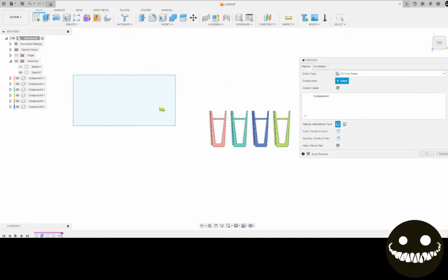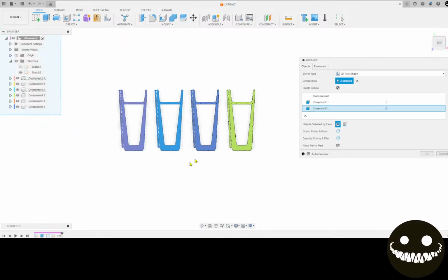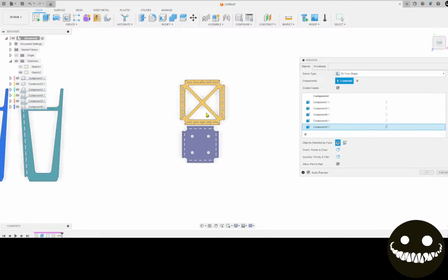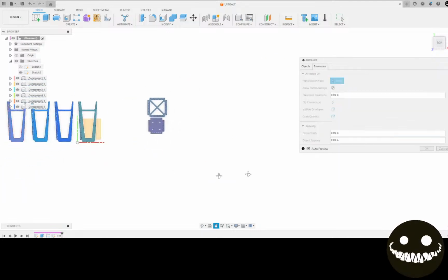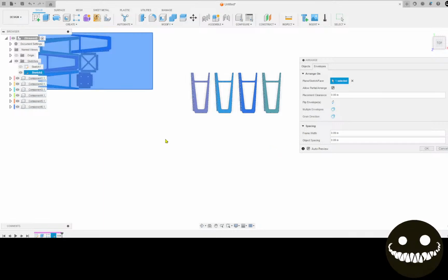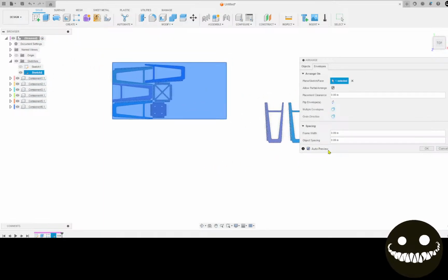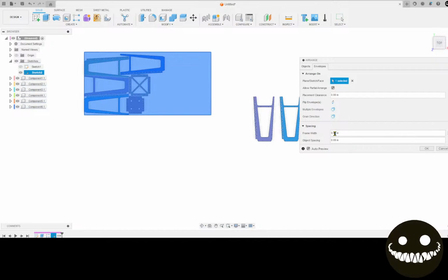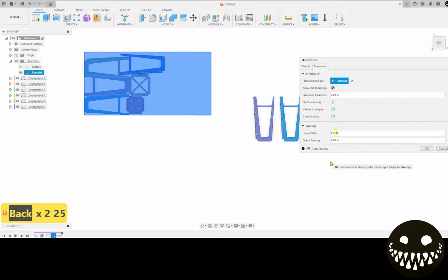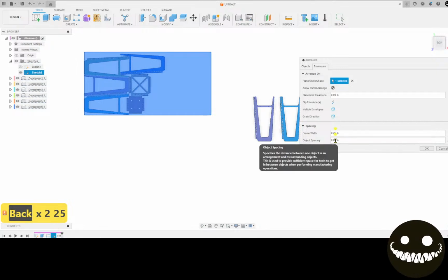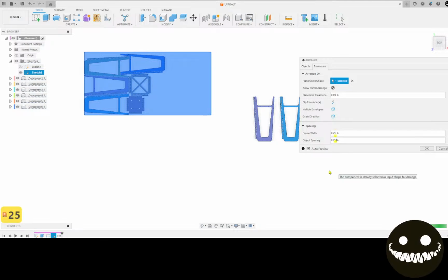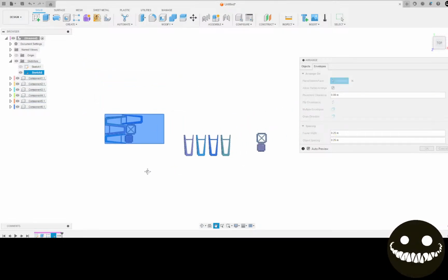Now what I'll do is go into modify and use the arrange tool. Select all this. And we are going to put it into this envelope here. Oh yeah, there's a nice tight fit. It's a little too tight. Let's do frame width of 1/4. Damn, you could almost fit 2 of them in a 4x8, couldn't you? 2 full ones.